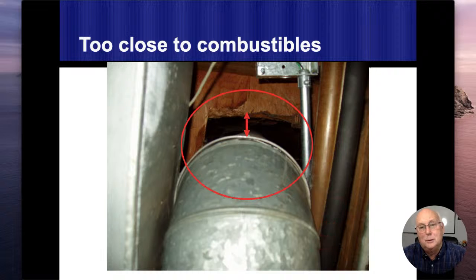I just had one yesterday. Two things on the vent connector. One is they had their suit that was in one of those plastic clothing bags that you cover the suit with to keep dust from getting on it. They had that hanging on the plumbing pipe, and it would drape over the vent connector and was literally resting on it.